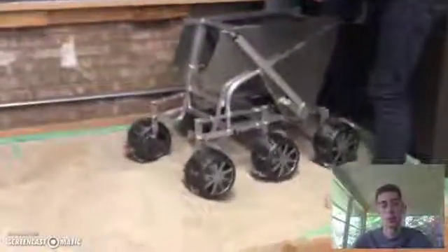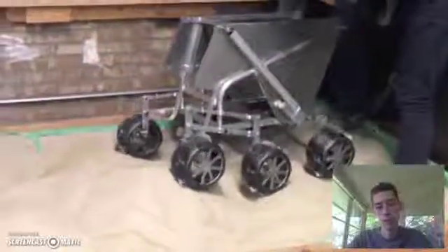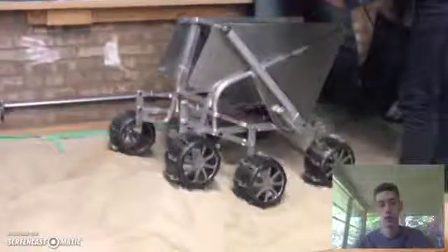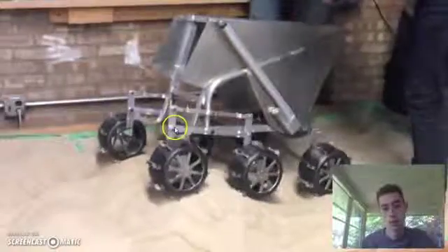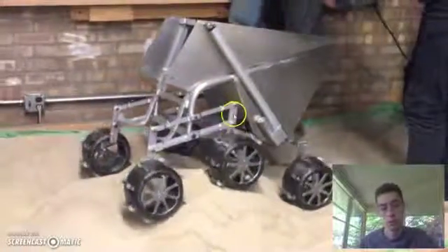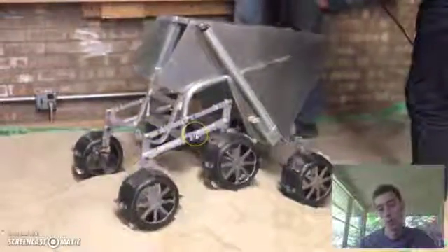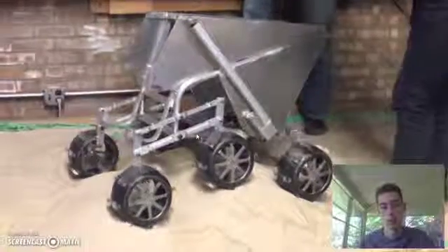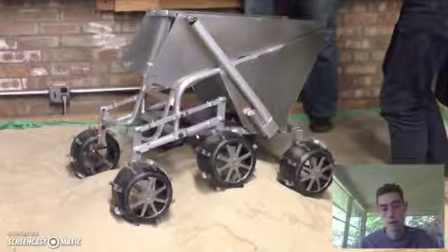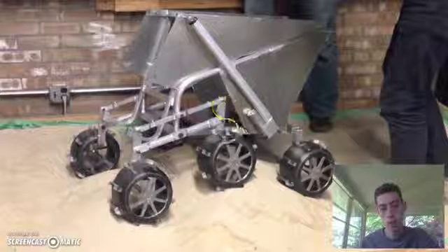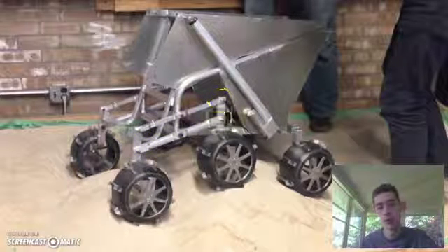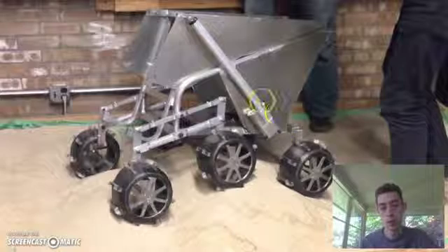So before going into our model, let's look at the system. So we see here that we have this closed kinematic chain, which serves as a basis for our locomotion system, allowing the robot to traverse chaotic terrain. From here, we have two parallel closed kinematic chains up front, which constitute the longitudinal bogies. In the rear, we have a transverse bogie, which is an open chain.